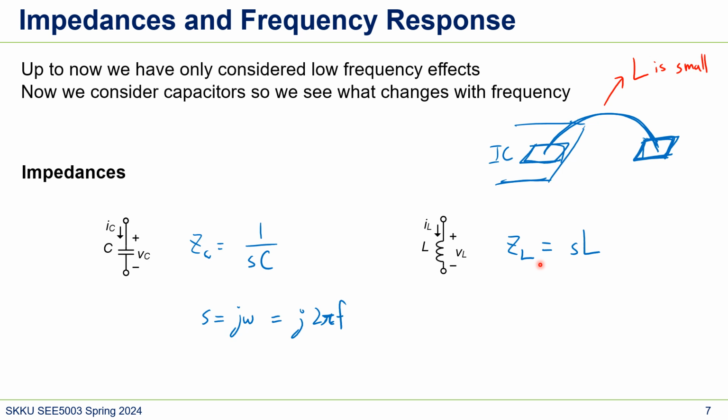As I said, the impedance will go up as the frequency goes up. So in high frequency, this bonding inductance may not be negligible. So again, the inductance can be crucial if our target signal frequency is high.